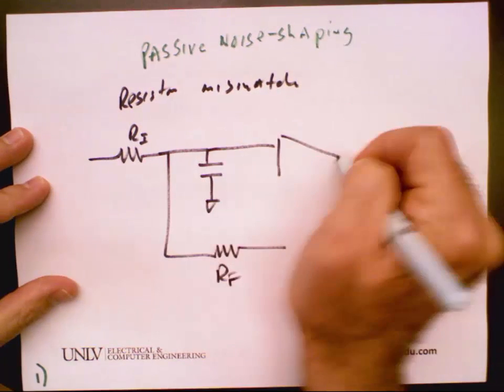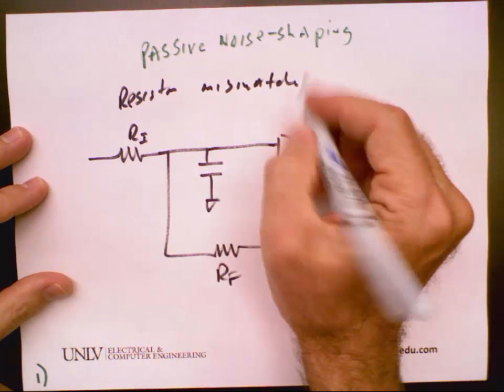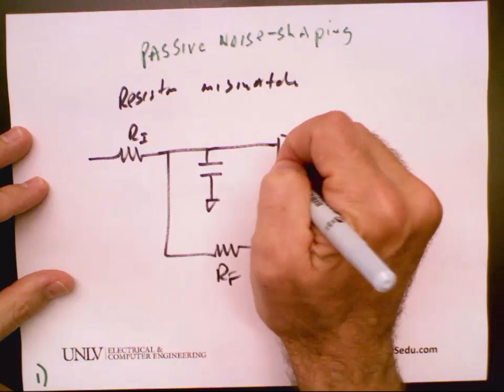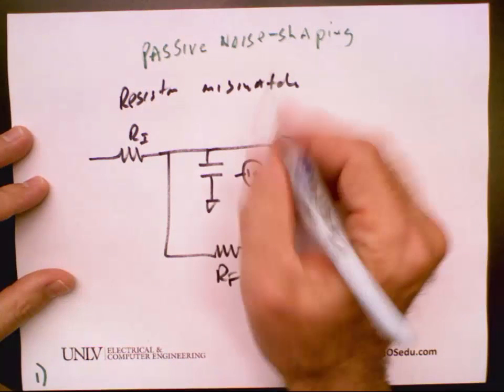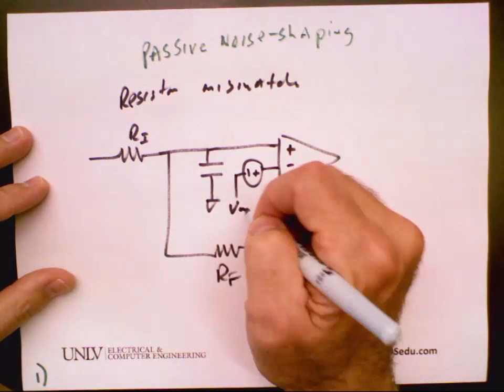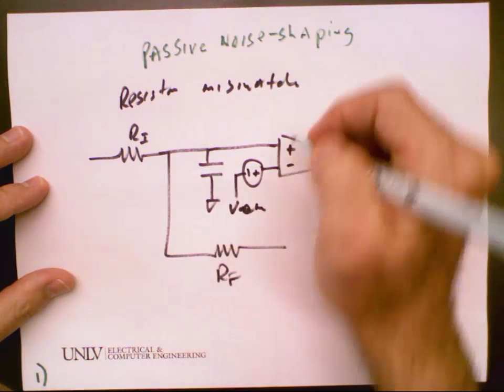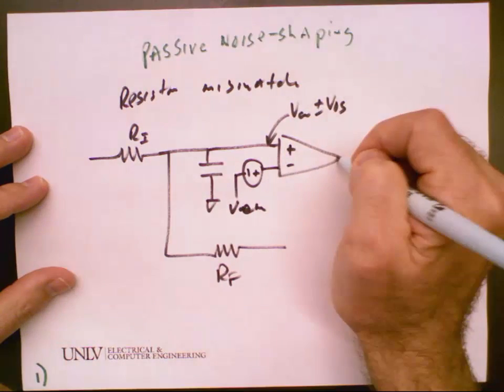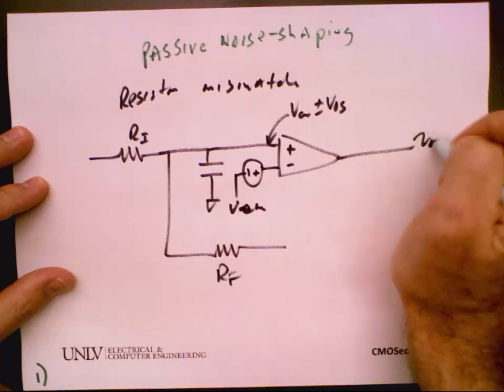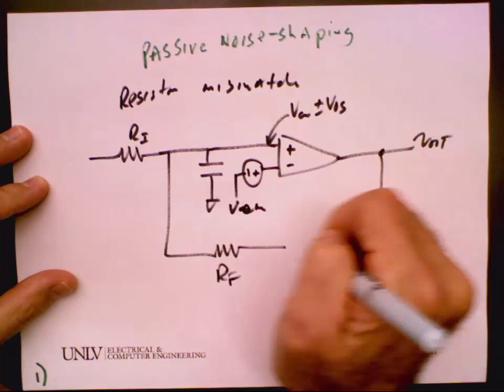Then you go to a comparator, and we got our plus, and then I'm going to use the offset here, which the comparator offset simply means that instead of this switching at VCM, it switches at VCM plus or minus the offset. And then we have our V out, and then that comes around here.